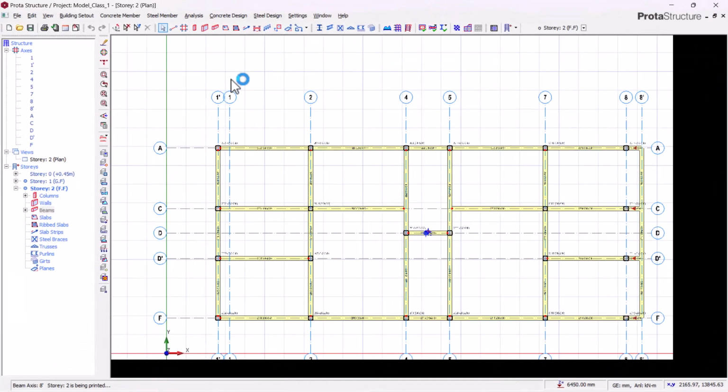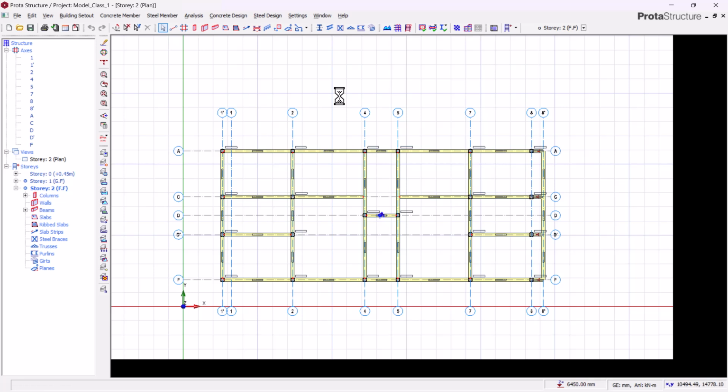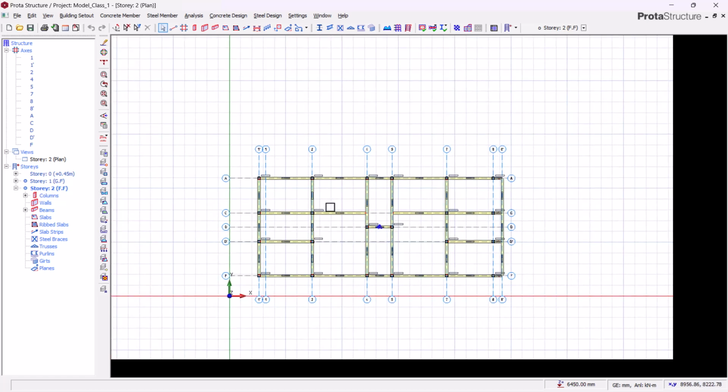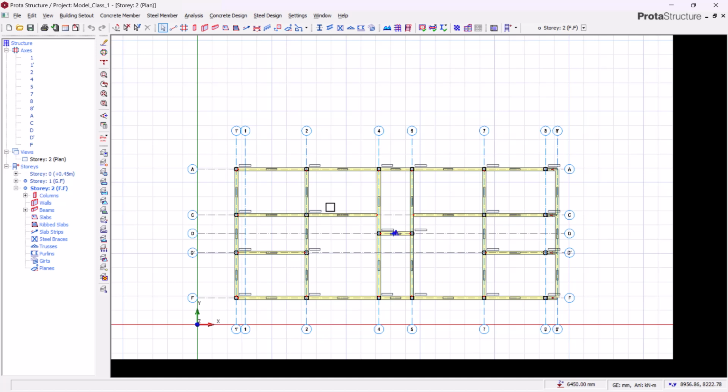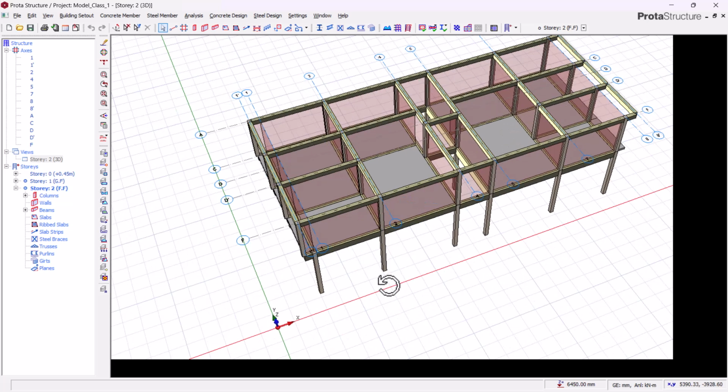So the next thing we're looking at is detailing. Design is very wonderful, but there is nothing as wonderful as detailing, because you can do all this beautiful design, all these reinforcements are passing, the concrete thickness is okay, but if you are not able to properly put this in a context that the artisans can read and understand what to do at every point in time, then the design is as good as you did not do anything. So detailing is very, very important. After this class, we'll be looking at how to properly transfer this into a detailing template and properly represent them, so our artisans on site can actually see what to work with and understand what to do at every point in time, just by looking at our piece of paper.